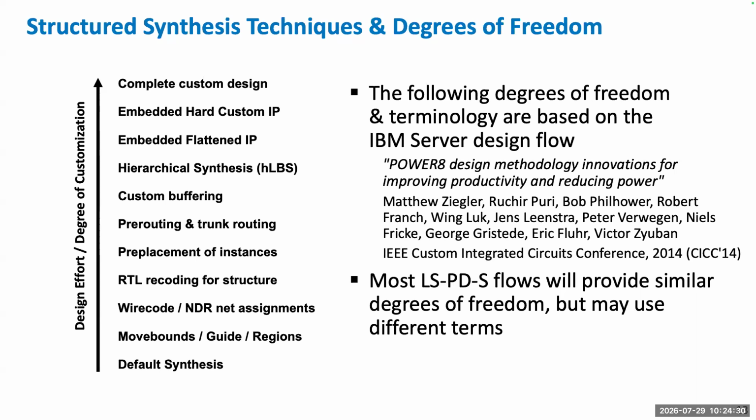I would always try what I would call default synthesis to start. The idea there being, let's see what the tool does. But if the tool doesn't produce the result I want, one class of techniques is borrowing from what I would do as a designer. The other set of techniques I'll mention are more automated flow script changes, but I'll walk through these to give you a sense of them.